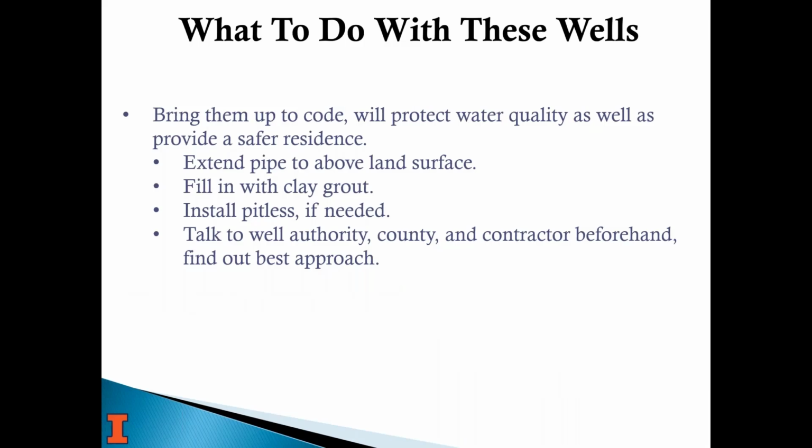So if you have one of these old wells, what we recommend is try to bring it up to code. Extend the pipe to the surface if it's in a pit, and then fill that all in with clay grout. And talk to your well authority or a well driller or contractor. Talk to county extension or your county health department or local health district. They may have some ideas, but using one of these wells is a risk.